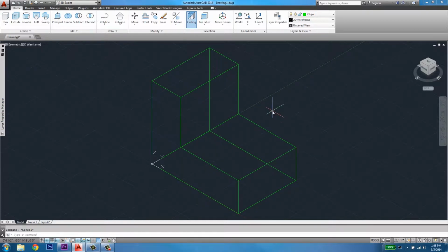While in an isometric view, type in UCS and then press Enter. As you know, this puts you in the UCS menu in the command line. This time, type in N for New, and then you'll see a different set of options in the command line. Now type in 3 for 3 point and press Enter. Now the command line is asking for an origin point. Think of this like a graphing coordinate system with an X and a Y axis.